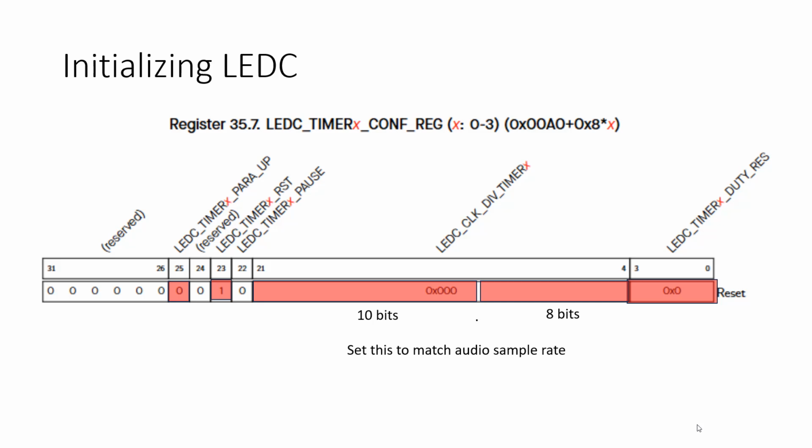So you can have a 10 kilohertz PWM signal, right, that's running at 10 kilohertz, and then you can have an 80% duty cycle, meaning the signal is high for 80% of the time, right? So make sure you have that terminology straight. There's the period or the rate of the PWM, and then there's the duty cycle. The duty cycle is actually the value that you're modulating onto the PWM.